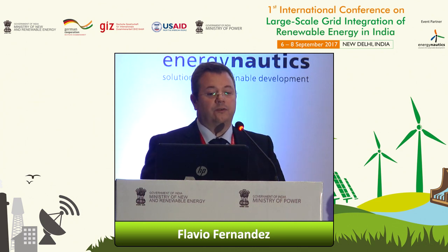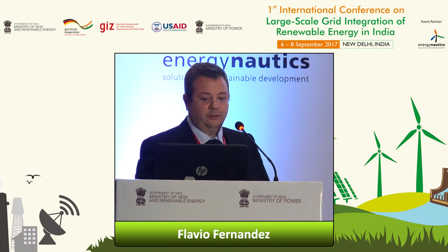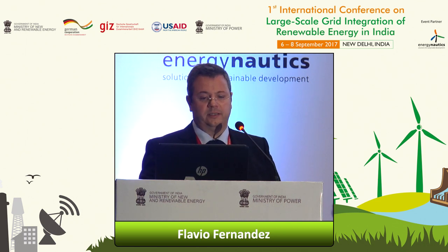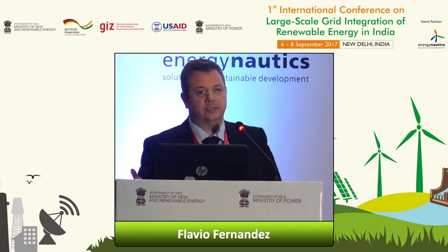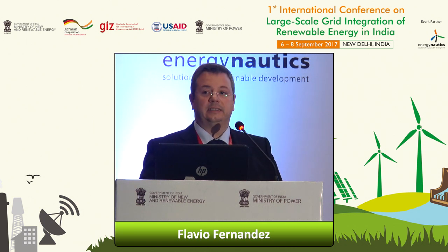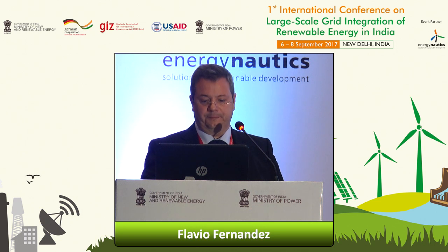So the generic model follows a modular approach. Here is just a simple representation. I took it from the IEC, but you have something similar for the WECC, where you define the different blocks. You see the control basically interfacing with different blocks. You have the aerodynamic part, the mechanical part, the generator itself, then the measurement equipment, electrical equipment, and also the grid protection. The standard will give you, for all the different blocks, how the transfer function should look, with different parameters, and then you know exactly what the model is doing.